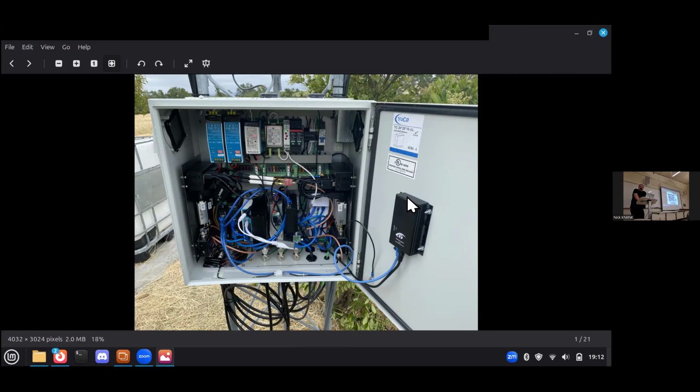If you said you wanted to make smaller boxes and reduce the complications, how would you split this into a few different packages? I do less stuff. If I can pare it down to just the ADS-B and the ACARS and VHF data link stuff, I can do it a lot more easily in a small box with like 4 to 6 SDRs and just a couple antennas.